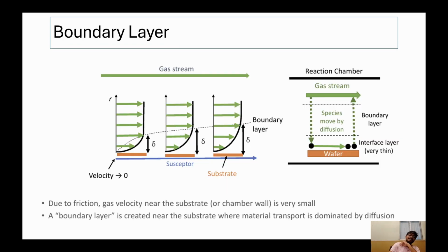So this stagnant layer is where there is no flow of the gases. Here is the laminar flow at this point, but here there is a kind of boundary layer, where these gases are stagnant, with very little flow, because at this position the flow of molecules is zero, the velocity is zero, near the surface.